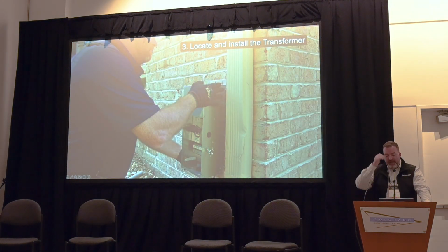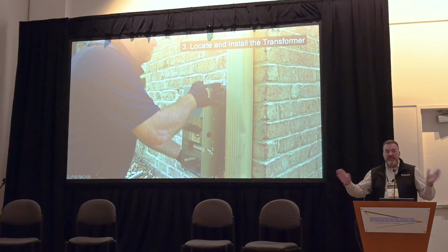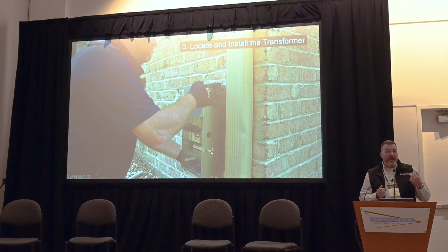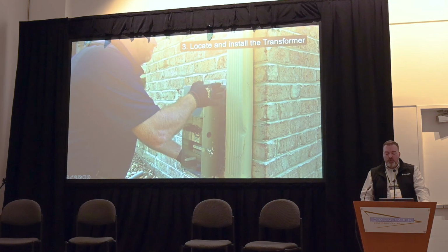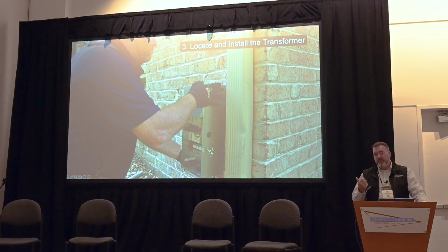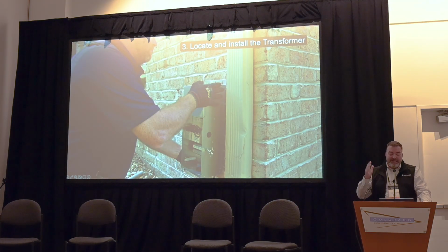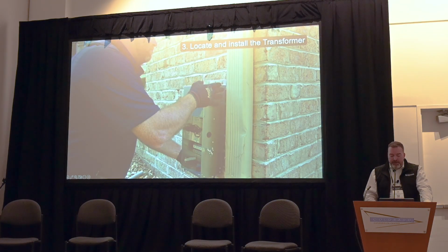Next thing you want to do is, now is when I start to split my team. We've gone over everything, everything's flagged, and I say, ready, break, let's go team. So in a two-man team, I have a tech 1 and a tech 2. During the split, tech 1, who's my lead tech, is always going to go through and install my transformer. He's going to unbox it, get all the controls out. If he's got to put in TAs, terminal adapters, lock nuts, conduit, he's going to take care of all that, getting it set and where it needs to go. He's just getting it all prepped.